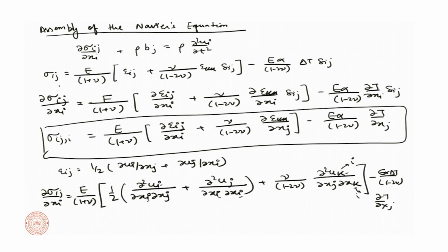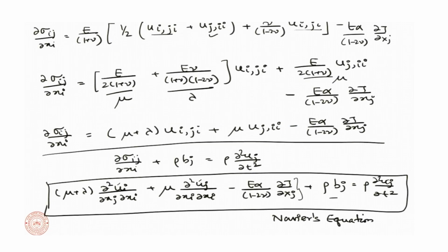If we dot it with the surface normal from both sides, we can then relate the displacement, which is a first order derivative with the position, to a value, and it becomes similar to a Neumann type condition. Now we have completed our Navier's equation, and we have seen an entire range of equations, second order in derivative with position and time, which can be used to model a solid mechanics problem. Now, let us try out a few examples.